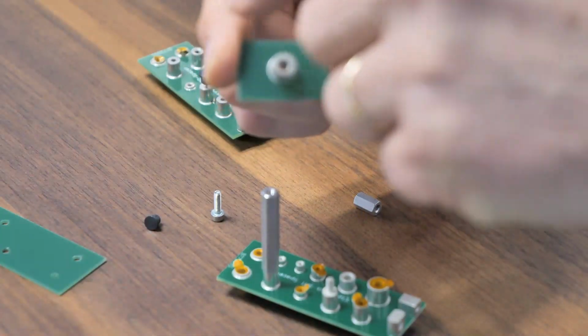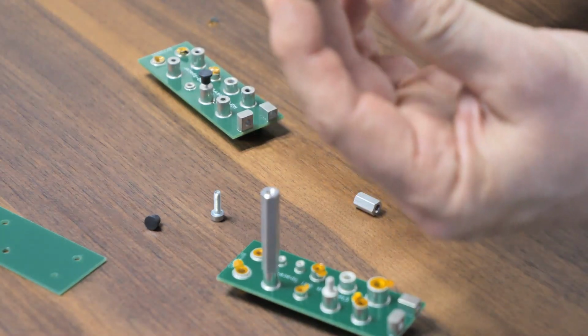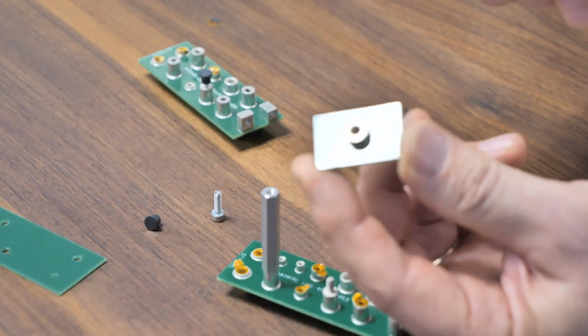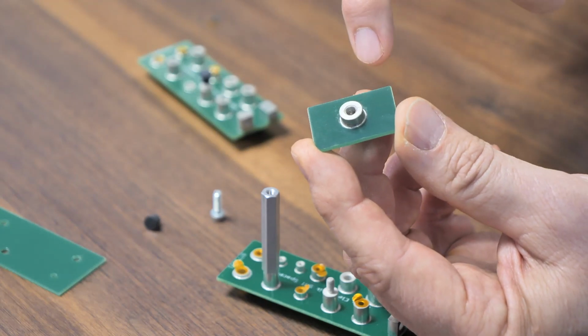It's not the height that counts. It's important that we have the solder all around the PCB or the component. This would be the perfect achievement if it's a closed meniscus.